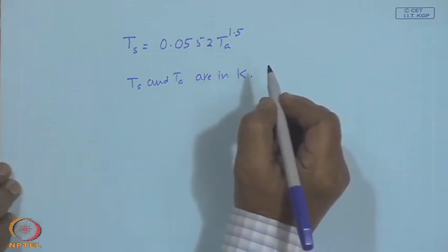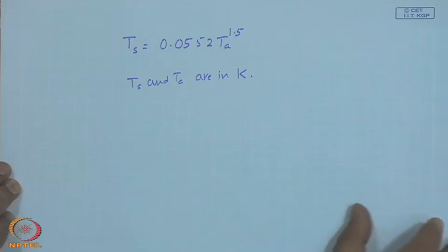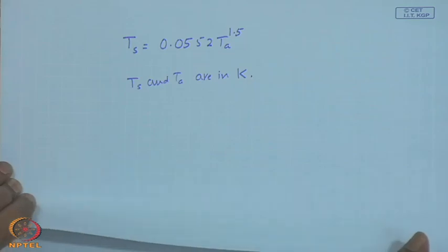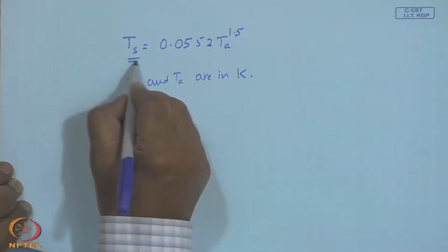In other words, this is an estimate. You measure the ambient temperature and you measure the temperature of, let us say, water kept outside, which is cooler than the ambient, and from there you estimate the heat loss, and that should have been lost by infrared radiation from the body under consideration, thereby giving you an estimate of T sky.